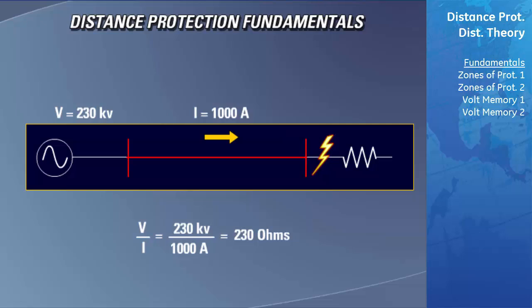In the example shown here, the fault is located after the transmission line but occurred before the majority of the power system load. Now the only impedance on this power system is the impedance of the source and the transmission lines before the fault.